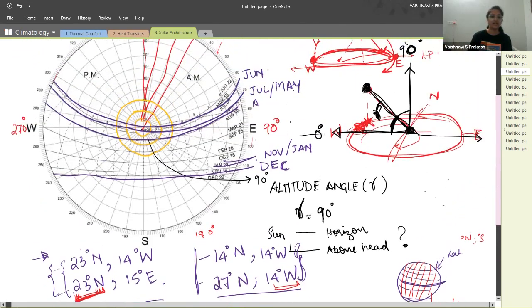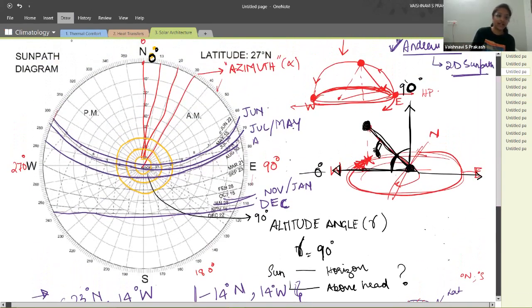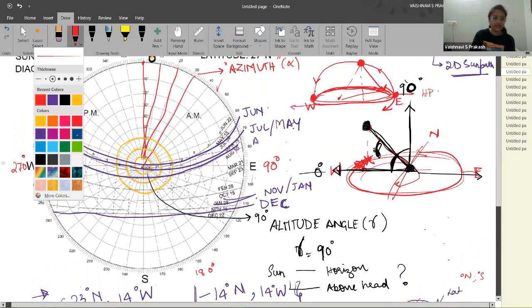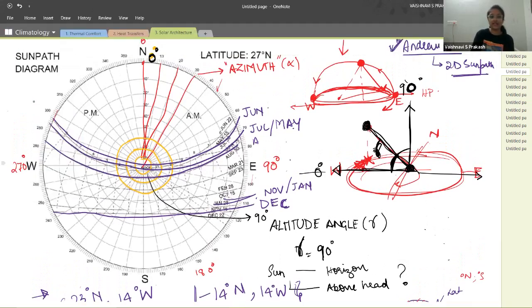Okay. So let's go back to the sun path diagram. There are more lines to look at. So we figured out the angles of the sun with respect to the azimuth. We got the altitude angles. We saw all the dates and the month lines. Next are these lines, which I don't know if you can see, but they're dotted. These are the timelines. These represent time. They're obviously from sunrise on the east to sunset on the west.